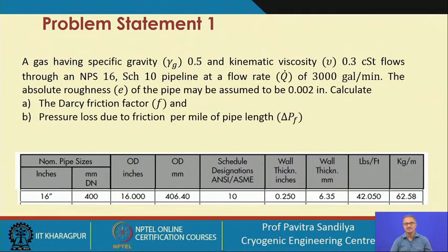Okay. And if you look at the unit of the kinematic viscosity, in SI units that is meter square per second. In the CGS system, it is centimeter square per second. Another one is centistokes. In case of dynamic viscosity, we use the poise, that is gram per centimeter per second, and in this case we use Stokes. Okay, this is Stokes, the famous scientist, from his name it came. So, this is given as 0.3 centistokes, that is 0.3 into 10 to the power minus 2 Stokes,